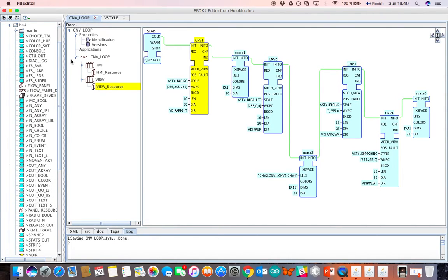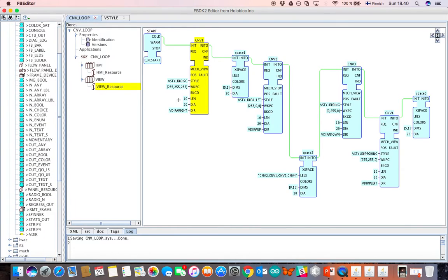and in the HMI folder we can check what can be used to provide the position value to the conveyors. Well, as I said last time, there are two categories of blocks which stand out from other blocks: the blocks prefixed with in and the blocks prefixed with out. In blocks are used to provide values inside of the application, in this case through the HMI, and out blocks to get values out from the application.